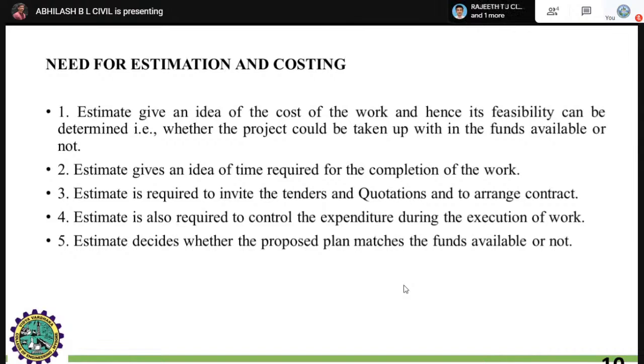Generally it might require around 10 to 12, just a general figure for a 60-40 site, right? For the particular foundation to complete up to the ground level, what is the time taken? Excavating, bed, placing of reinforcement, later adding the columns, then the formwork completion and the curing part. Coming to the curing part, it might take around 28 days to 1 month. This is how the starting stage of the foundation itself takes place.